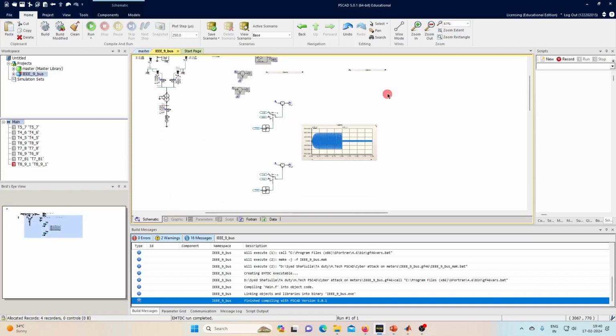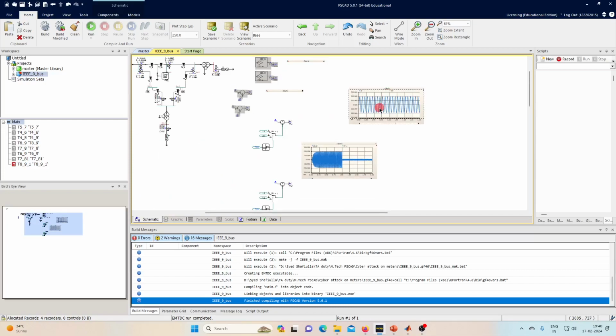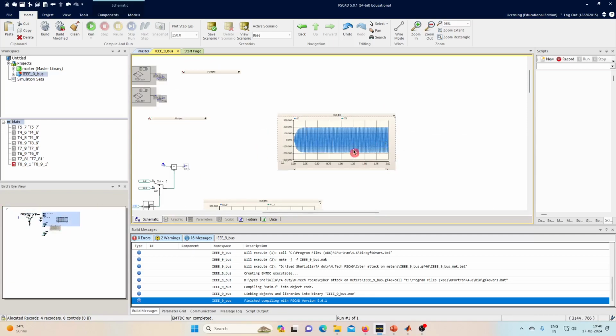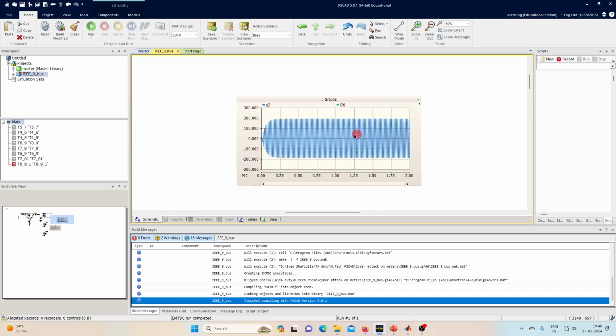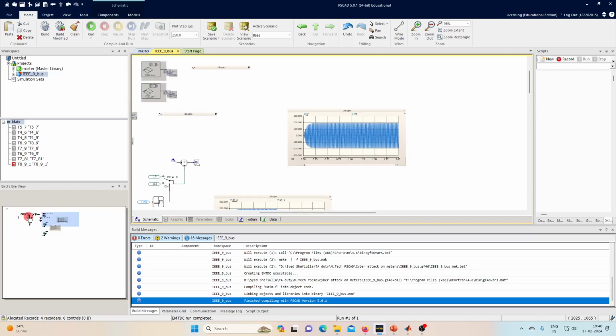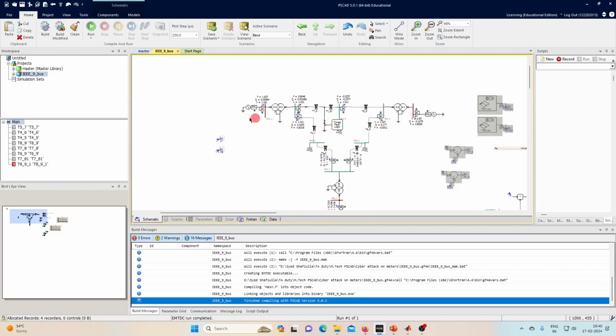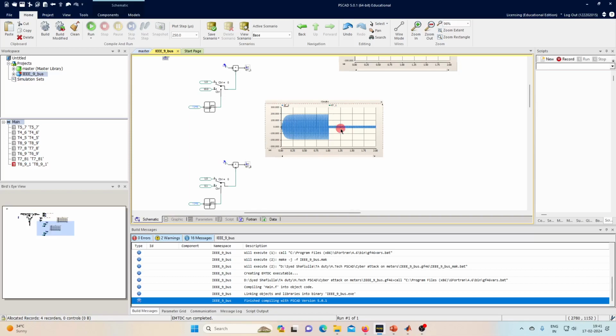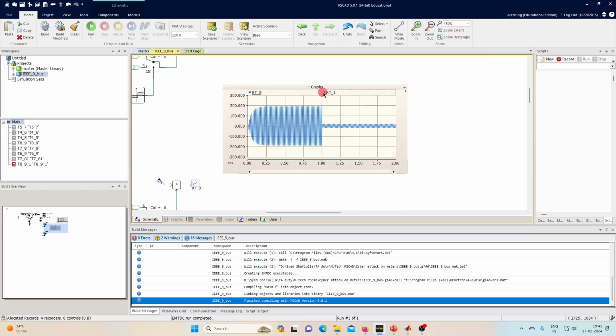If you see the actual measurement, there is no change in the actual physical system practically. There is no fault, nothing. But due to this kind of CTPT cyber attack in the real-time network, the relay will think it has a fault and it may produce a trip signal to the circuit breaker.